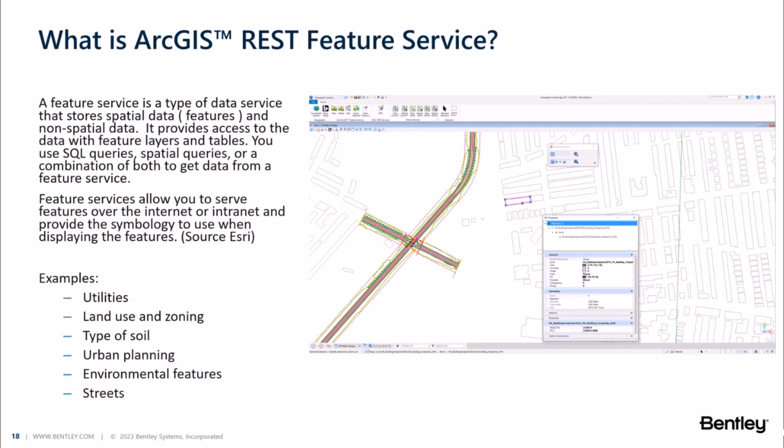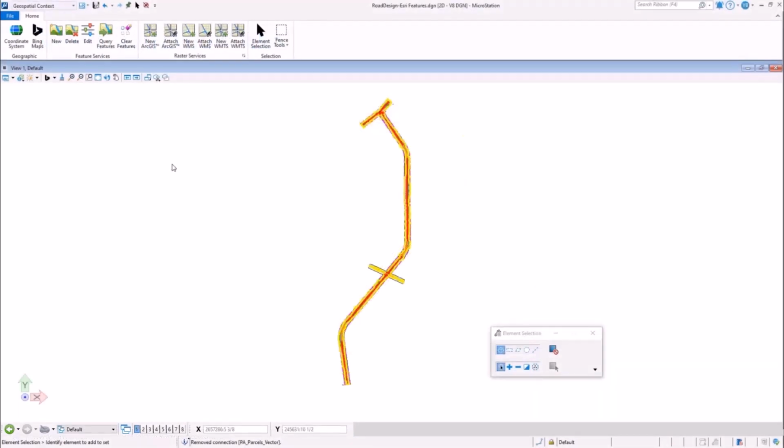If an entity is modified on the server, its local copy will not automatically be updated. It will be updated the next time the query tool is run by the user. These elements are seen as read-only by MicroStation tools. The special clear features tool should be used to remove the queried features from the model. To include any of these features in their design, the user must pick up a copy that will be disconnected from the feature service.